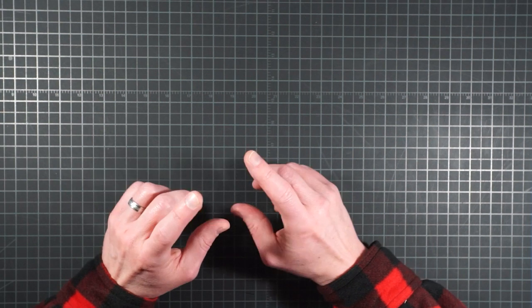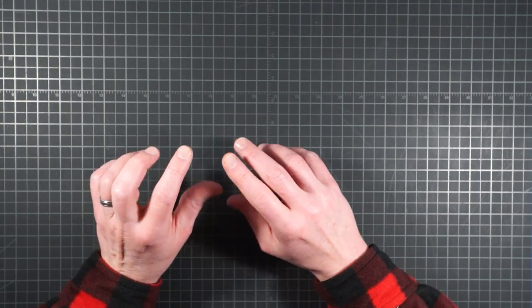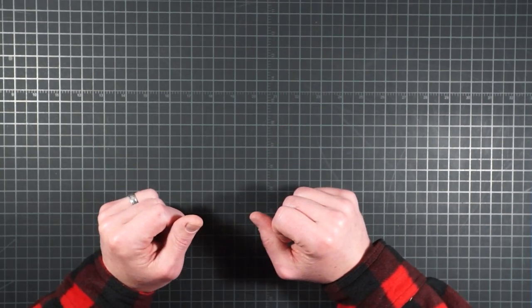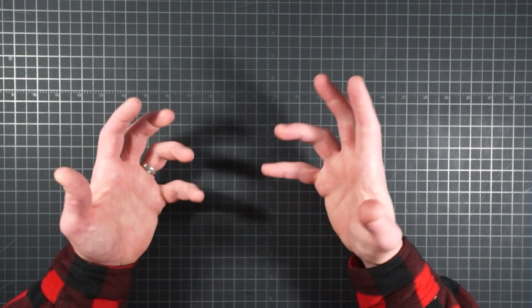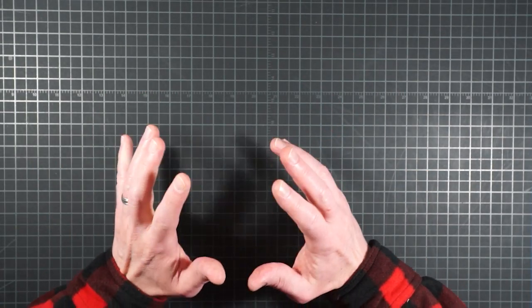And just a couple of other theoretical issues to be aware of if you're going to use a filter with this type of technology. Again, with a diagram from the sustainable sanitation presentation while quoting from the chemical engineering paper, "to be adsorbed, an adsorbate molecule must find its way to the adsorbent particle by convection, diffuse through the fluid film surrounding the particle, travel by diffusion along the length of a pore until it finds a vacant adsorption site, and then adsorb onto the solid surface." It's a multi-step process, and the point is that it's not instantaneous.